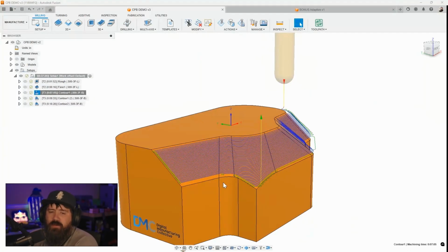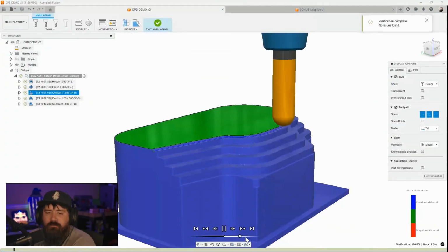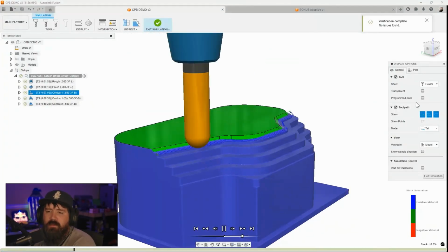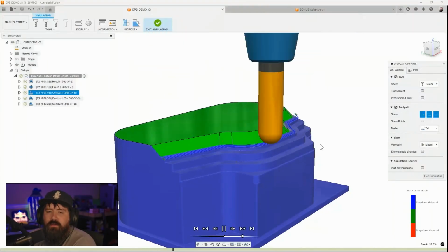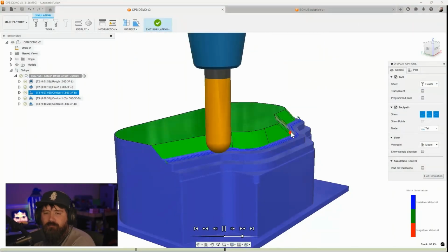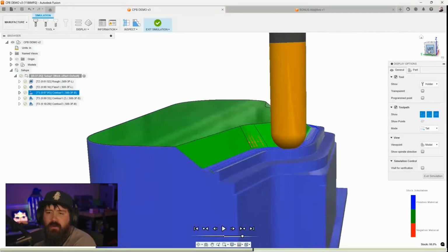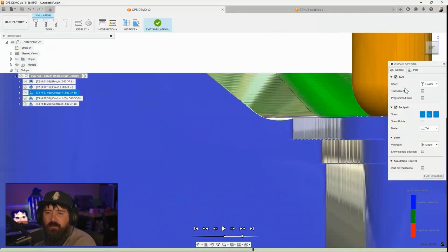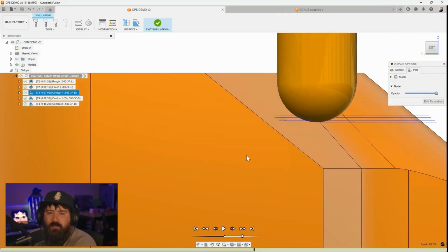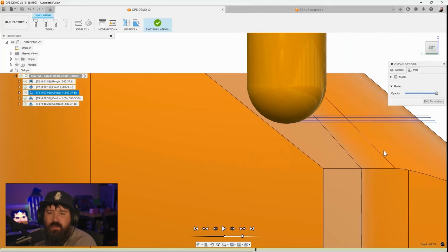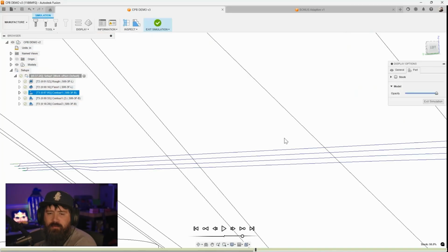One of the things we do when we're drawing toolpaths like this, or drawing the blue section of the toolpath, not here in the stock simulation but when we were looking at that toolpath earlier, is we're showing the tip of the tool. We're not actually showing the contact point. So if I drag this around and go to the side, and maybe turn the stock off for a second, as we come over to this corner and this edge, which is a little bit hard to see, we have essentially the tip.